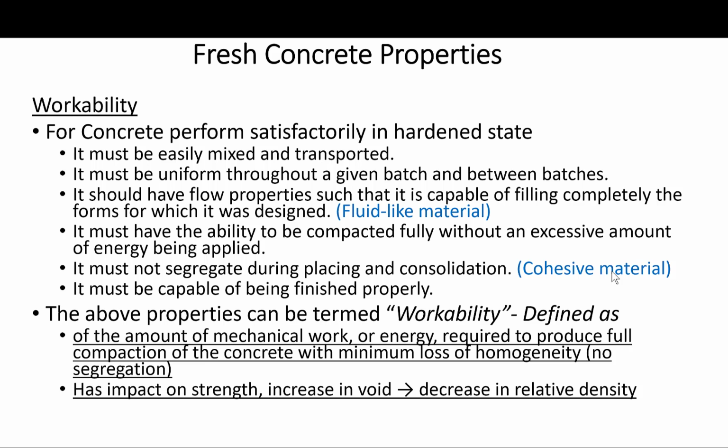Okay, so let us discuss workability. So again, from the standpoint of a finished product, for hardened concrete to be of an acceptable quality for a given job, the fresh concrete must be capable of satisfying the following requirements. It must be easily mixed and transported. It must be uniform throughout a given batch and also between batches.